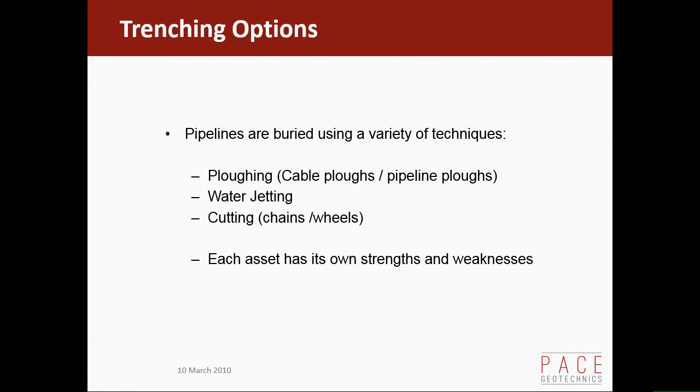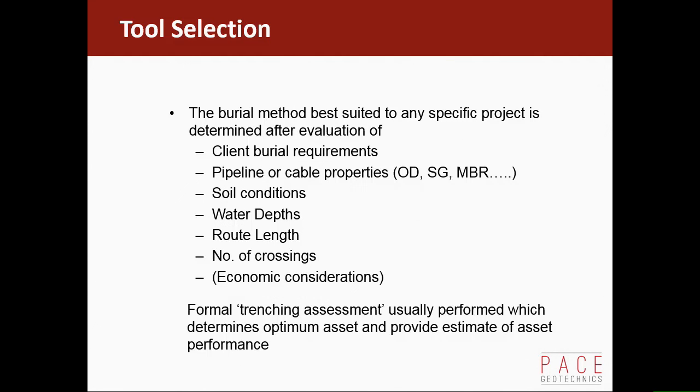What I'll do now is spend a few minutes talking about plough or trenching. There are 3 main methods for trenching: ploughs, water jetting cutters or trenchers, and then cutting machines, trenching machines often. Each has their own strengths and weaknesses, and there's several cases where one will be more suitable than the other. So we need to select the right trenching tool.